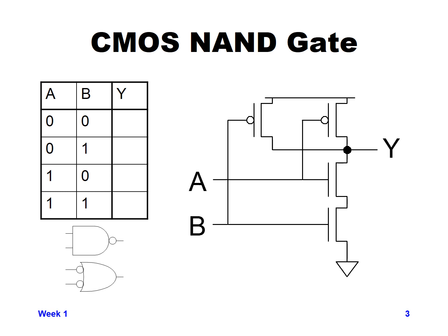Now in this case, the gate of one of the NMOS is connected to one of the PMOS, and that's connected to an input signal A. The gate of the other NMOS is connected to the other PMOS, and that's connected to input signal B. Again, the right-hand side shows the transistor level diagram. The lower left-hand side shows the 2 different types of symbol diagrams that you can use for this logical function.